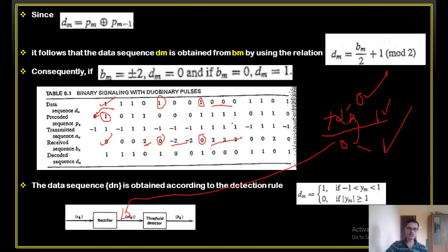This is the modified DuoBinary code where the symbol detection depends only on the current voltage level. But in the previous case, the DuoBinary signaling method, the symbol detection depends upon the previously obtained bit also. So that's why the error was propagating to the next symbols.